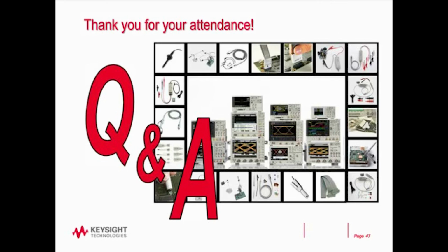Now that's talking about specifically doing the switching analysis. Now, as we talked earlier about the power rail measurements, that's a 2 gigahertz probe, so you could get a 2 gigahertz or higher scope to make those type of measurements if you're trying to look at extreme power integrity in a high-speed digital system.